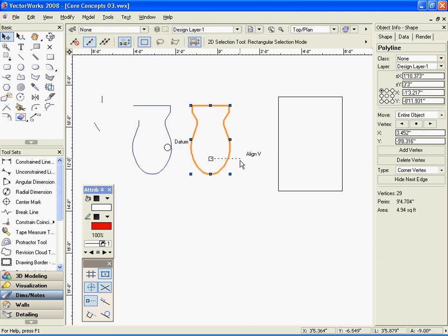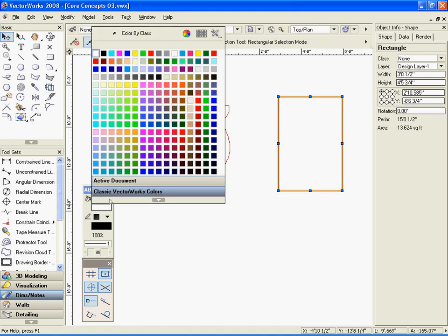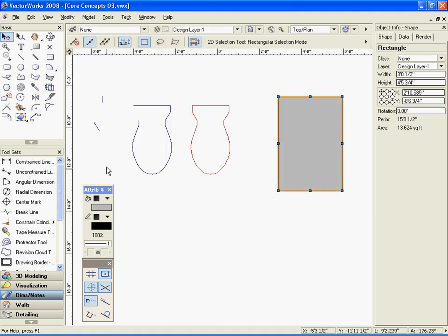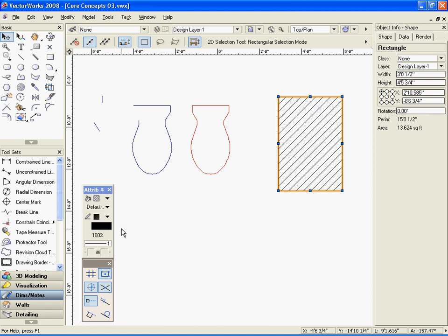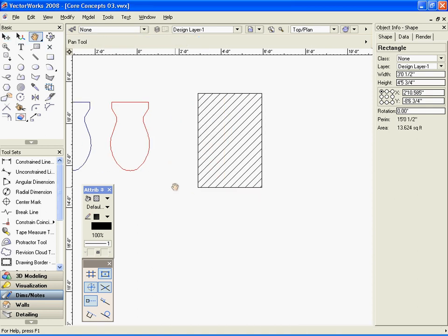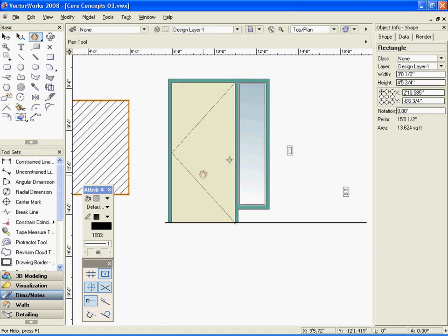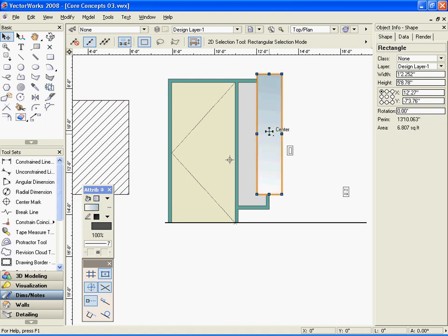Often, the fill of these objects will be white, but through the Attributes palette, they can also be given a color, gradient, picture, pattern, or hatch. An object's opacity can also be adjusted in the Attributes palette. Surface objects can also be stacked on top of each other, and having a surface fill means that an object will be solid, not just a wireframe, when it's transformed into 3D.